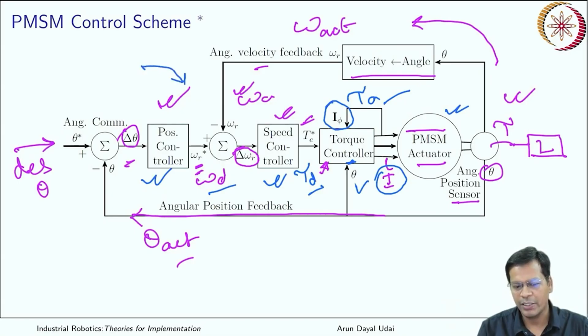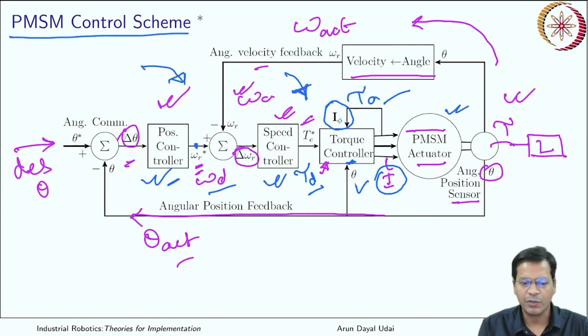Okay. So yes, you can have some desired input velocity fed in between over here. Instead of calculating the desired signal, you can feed velocity directly from here. You just have to discard the outer loop before that. Similarly, you can have a desired torque which goes here, and you just have to ignore the rest of the upper loops. Okay, so direct torque control is possible. This is a permanent magnet synchronous motor control scheme, which is normally embedded inside your standard AC servo motor driver.